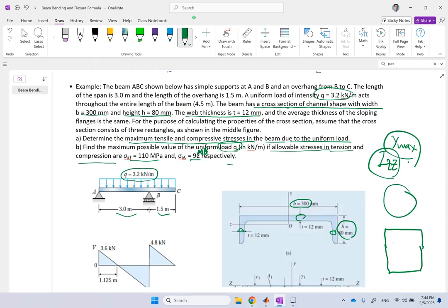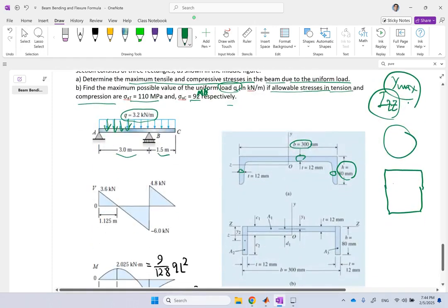Now, one thing I have to mention here is this is clearly not a uniform bending. Why not? Because there is shear force. And as we learned, when there is shear force, bending will change. Okay? Bending will change when there is shear force. So here we are basically doing some approximations. It's not perfect. And what we do, we only look at 2 points on the beam, and we only use the single M numbers in those locations and not treat the whole thing as uniform bending.